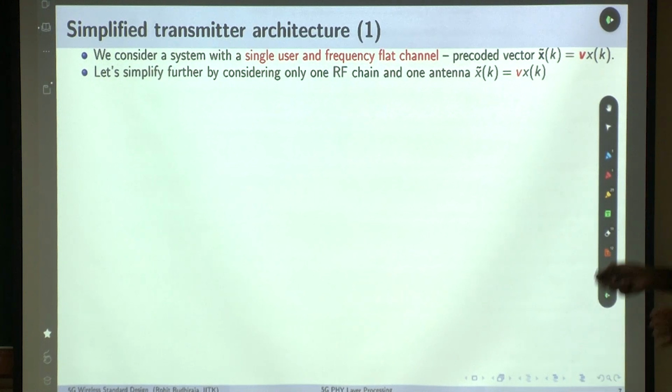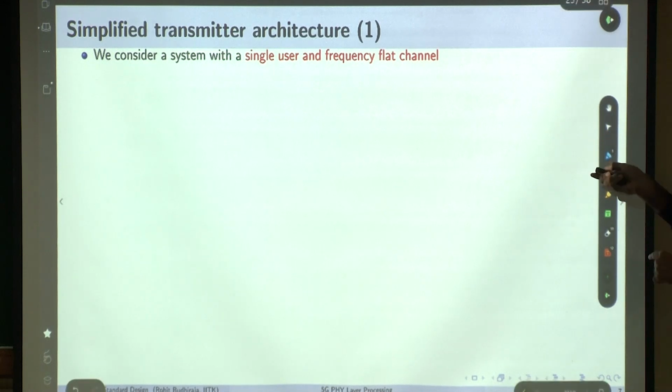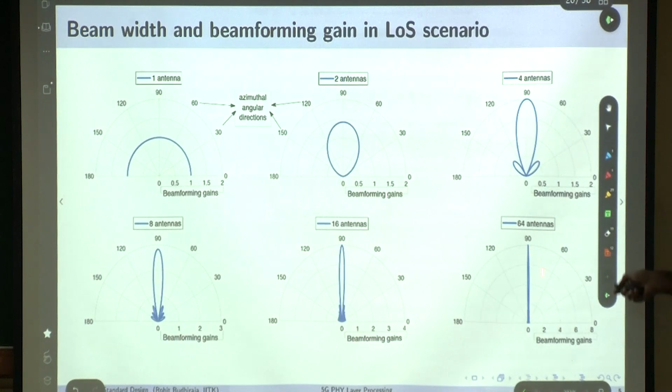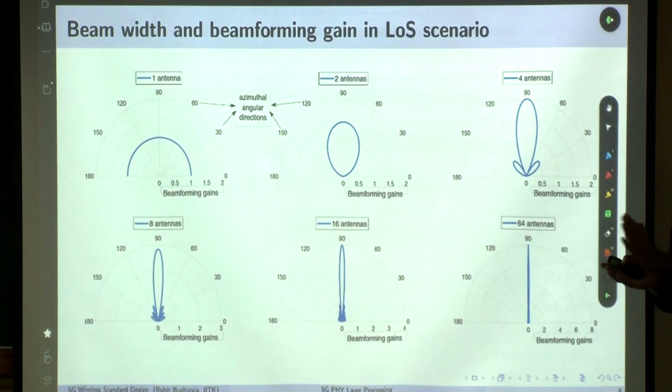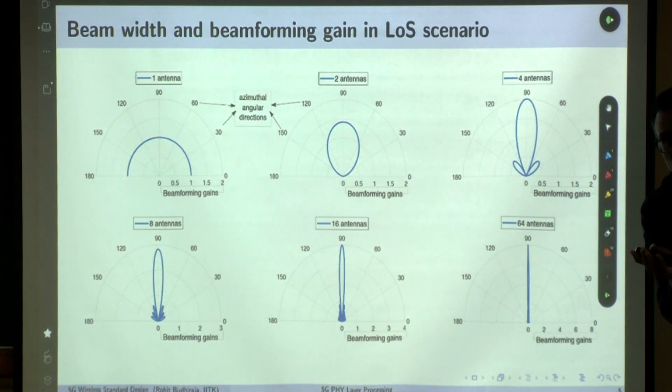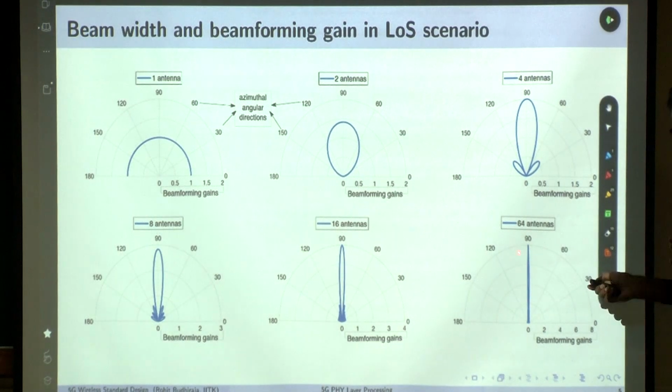I have to do this pre-coding. Even before we talk about this, why is this pre-coding necessary? Let's go back. You have 64 antennas, right? You will pre-code the signal to combine it. The base station has 64 antennas. How are you forming this sharp beam? You are combining the signal, and then forming a sharp beam. And this is basically the MRT. That's what it is.